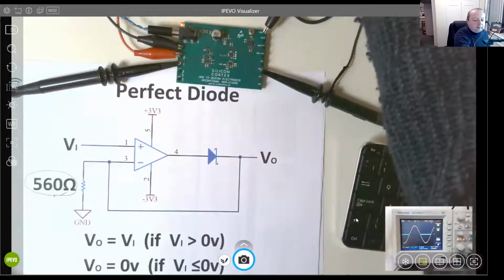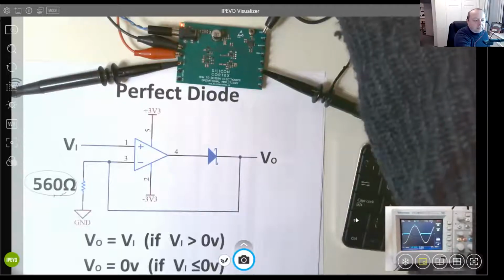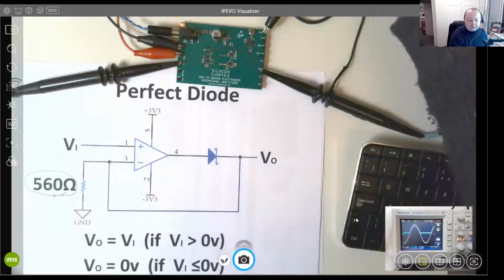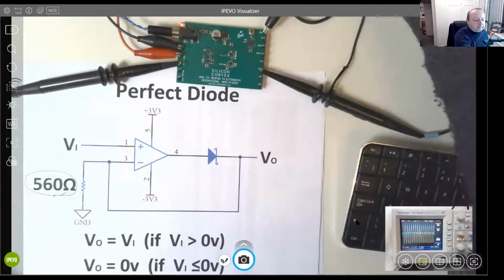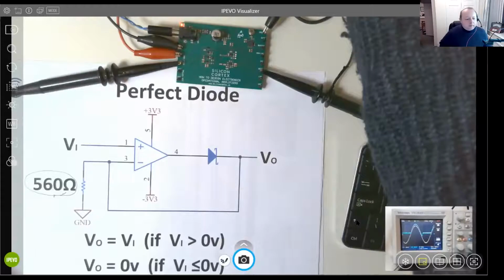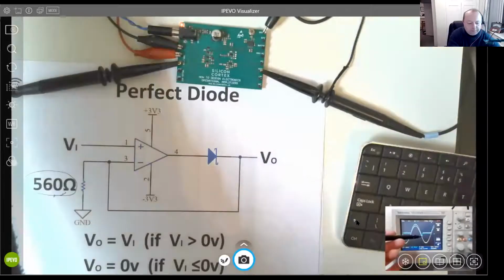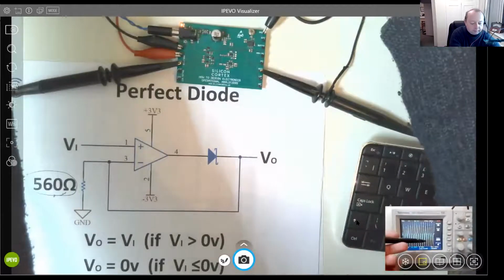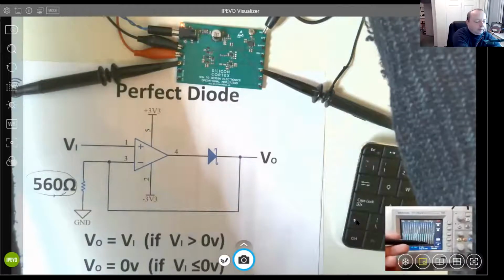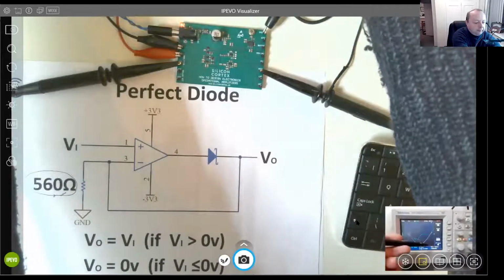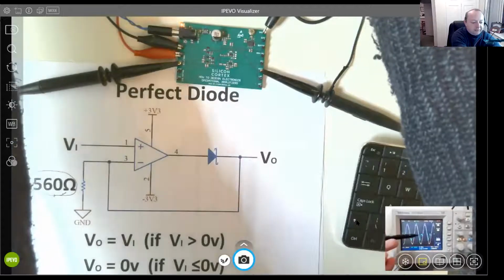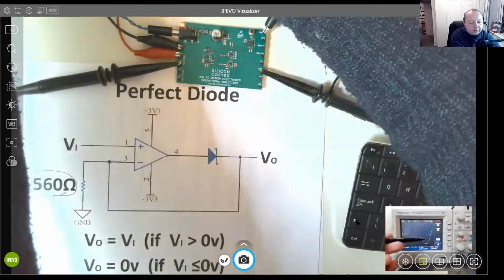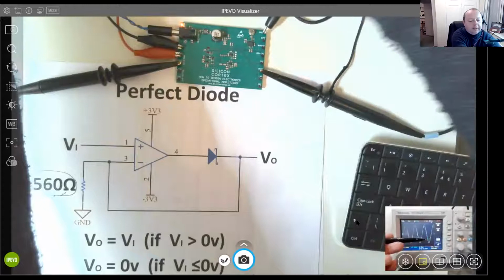There we go. Right, so there it is. So there's our perfect diode. I just set it above there so you can see that bottom right. If I start to increase the frequency, I've discovered that things start to go horribly wrong. And I'm going to go up to about 3 megahertz. Oops, this one here. Look, and now you can see I'm now getting a negative voltage out of it. And yeah, the whole waveform is starting to get extremely ugly.